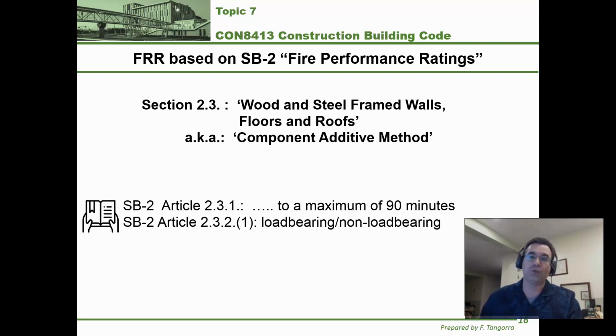A non-load bearing one is a type of structure that if you knock it down, nothing happens. So an example, on the top story of your house, typically all the walls except for the exterior walls of the top floor of a house, typically are non-load bearing. That's why it's easy to remodel the top story of a typical house in Canada, to add a bathroom or remove a bathroom or make rooms bigger, because none of those walls are load-bearing. You can knock them down and the roof is still fine, because typically the roof sits on the outside walls.